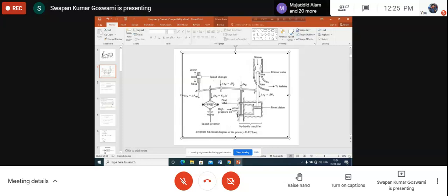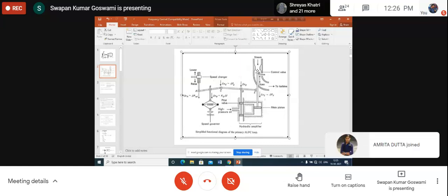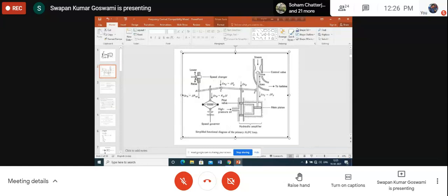And when we discussed the oscillation of the synchronous generator, when we started discussing the active power control, then again there will be speed variation of the synchronous generator. Sometimes it is more than synchronous, sometimes it is less than synchronous, and finally a steady state will be established when the power output becomes reduced compared to the initial power output. So because of the power decrease command in this mechanism, the power output of the generator will be decreased.